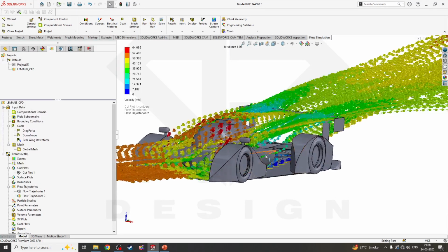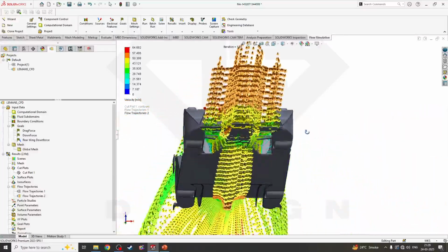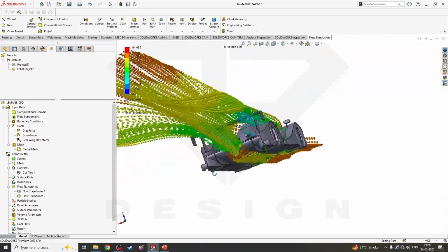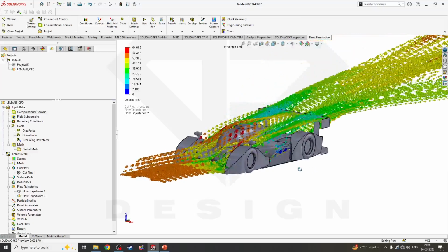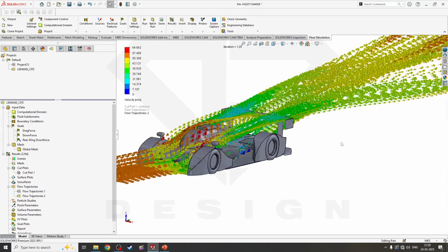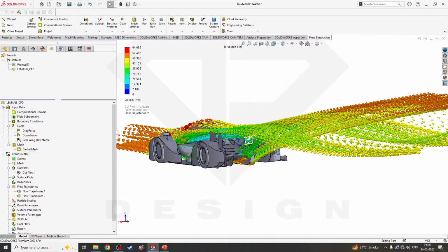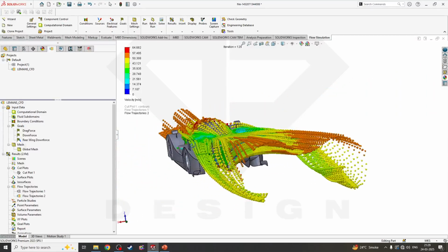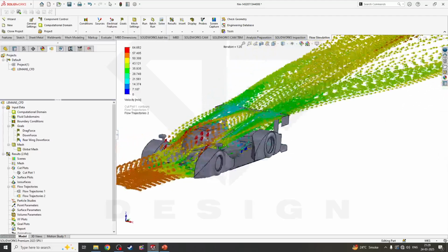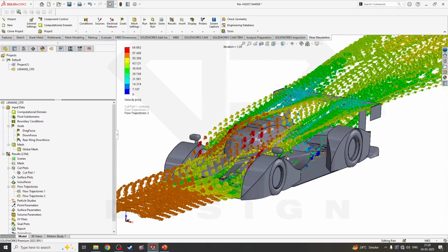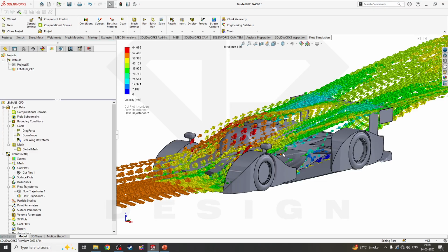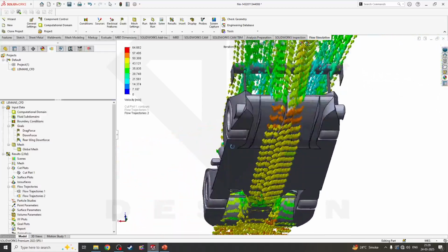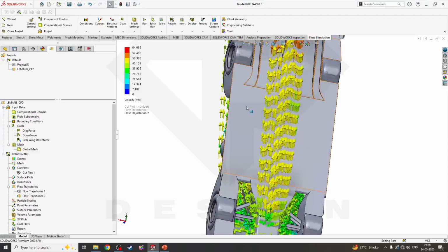I just explained how to do the aerodynamic simulation, so that you can start with simple airfoils. Try different airfoils and try to measure the drag force, down force, and also the turbulence behind it, and you have to study the pressure contours. According to that you will develop an overall understanding of aerodynamics. If you want to pursue your career in aerodynamics, then you can start learning this type of thing through different studies. Also a diffuser you can make.